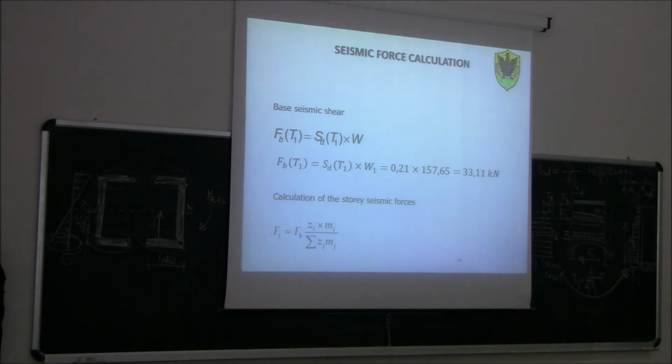Okay? So when we design a light frame building, I say this not necessarily for this course. For this course, I'm happy to do only the seismic design. But when you do a calculation as an engineer, please don't forget to do the verification for wind, particularly also for cross-lam, but particularly for light frame buildings. Because usually the design is governed by wind more than seismic. Okay? Particularly if you use a q factor of 5. Okay, is it clear?